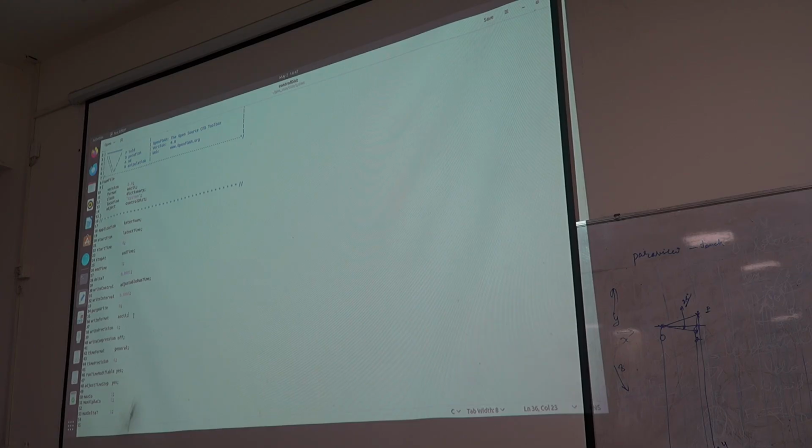Then writeFormat, earlier you can see purgeWrite is 0 because I want to keep all the files. If I am only interested in the final output file, then I will go for the purgeWrite option equal to 1. Write format, earlier you can see the format was binary, now we are writing in ASCII format. So it allows different formats.